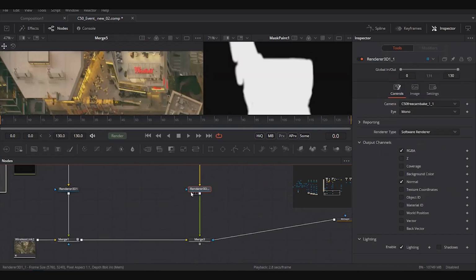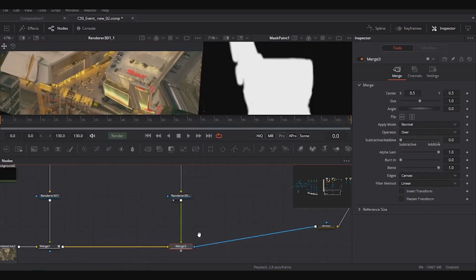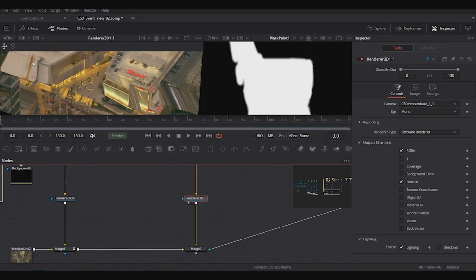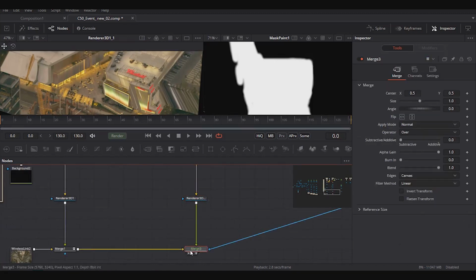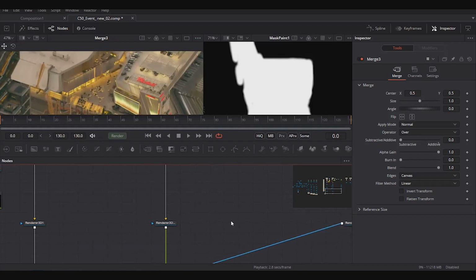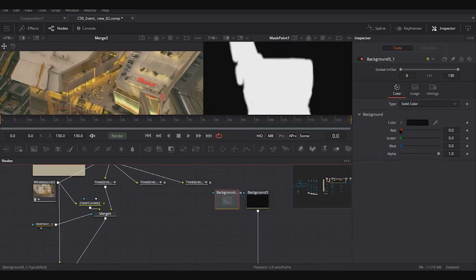And when we come down here with the renderer, we're obviously rendering everything. And as we merge this over the top, we need to create a mask, so only the new bits are being applied. So go up here to this mask area, make this fully white,